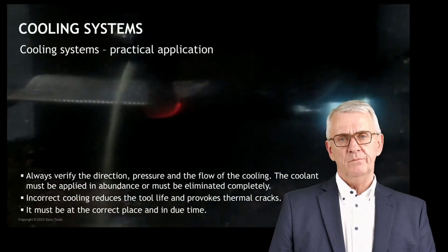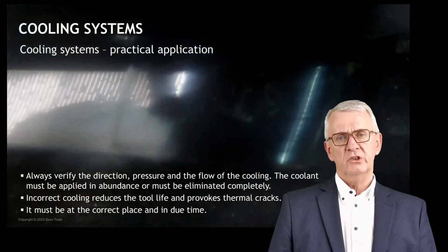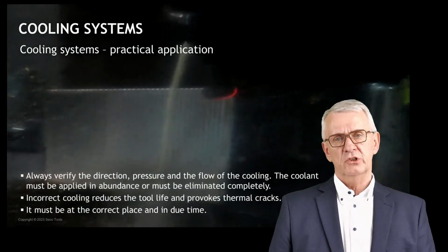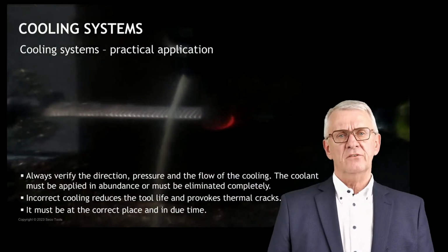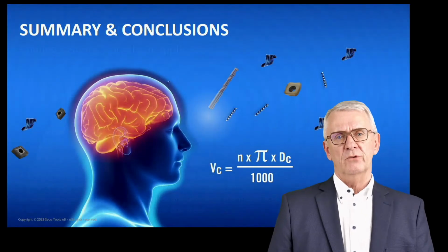It should be well in time. Cooling should start before machining starts and should stop after machining stops. All that kind of practical stuff, you know, if you do it well.